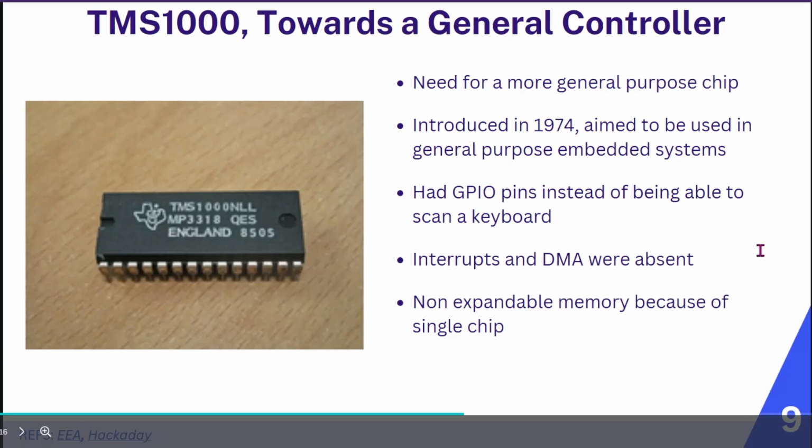The TMS 1000 family used masked program ROM. Hence, once the user had debugged a program ready to be committed to production, they would send the program to Texas Instruments, who would then make a special mask to program the on-chip ROM. The ROM could not be altered in the field. The contents were fixed by the patterns laid out on the chip by the manufacturer. While this process had an initial high cost, the production cost was very low, making it suitable for high volume products, say more than a few thousand items sold per year.